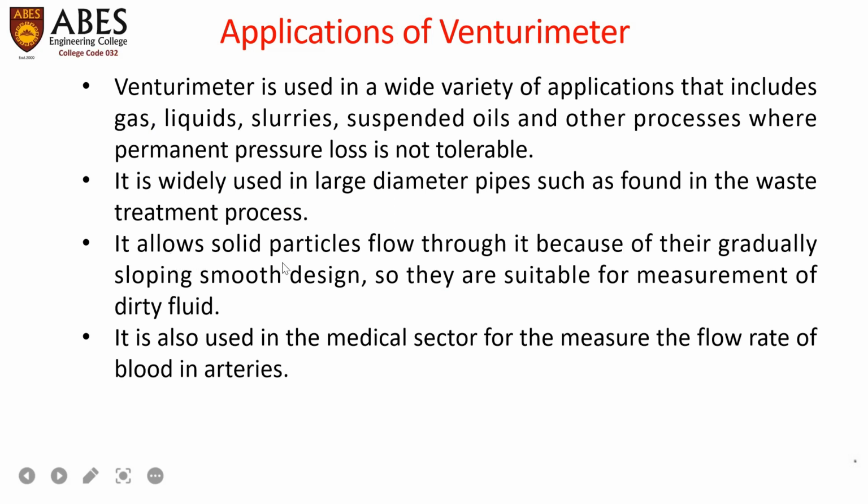It allows solid particles to flow through it because of its gradually sloping, smooth design. So basically, due to the gradually sloping design, it can be used to allow the flow of solid particles. So it is suitable for measurement of dirty fluids. Whenever there is a slurry or dirt in the fluid, it can be used easily to calculate the flow rate.